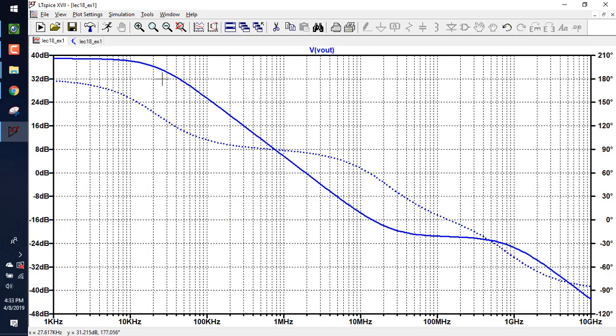So I'm at, say the phase, it's 3 dB down. It's a little bit lower than that, but let's just say it's right here. And I start 1 decade earlier at 2, and that's approximately when the phase starts rolling off. When do I expect the phase to start to flatten out? About 1 decade later, or about 200 kilohertz.